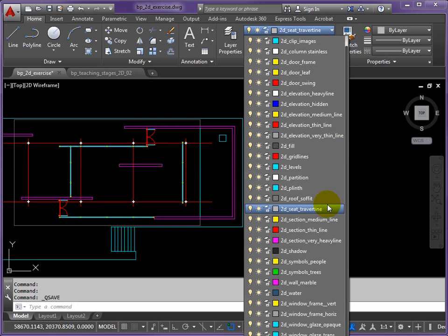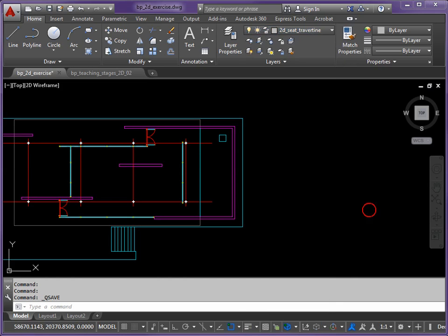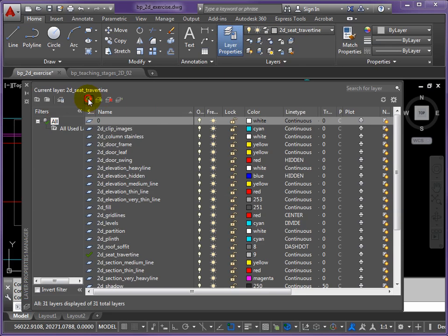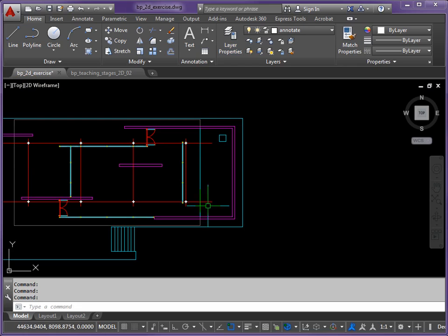Okay, I'm going to change layers to the annotate layer. I would do it if it was there. I don't have it. Okay, so we're going to create that layer first. So a new layer, and let's call it annotate. So I'm just using this for general notes and other graphics. Okay, color white will be okay for this. So I'll make it current. Close that. Okay, so we're going to mark a section line vertically through here.